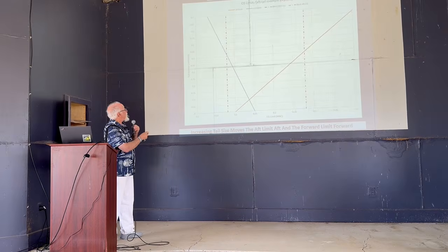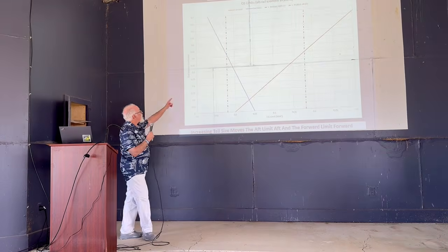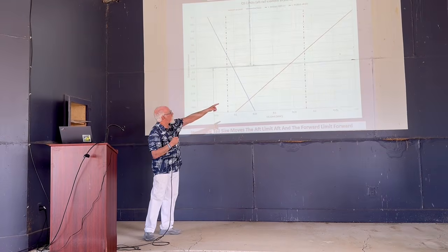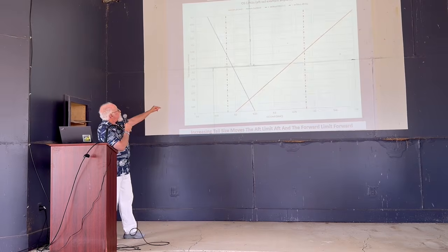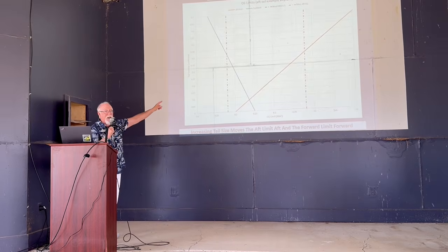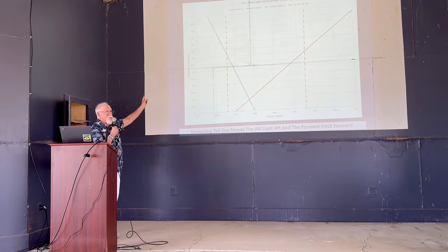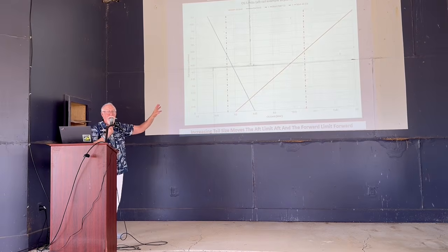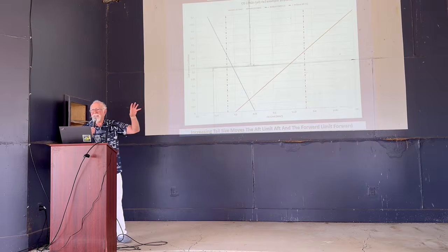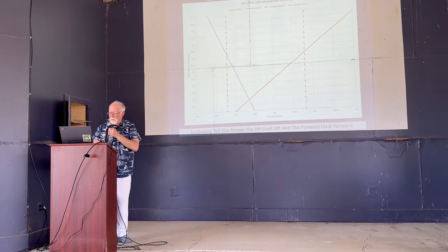And basically what you want is you can pick a tail size or a tail volume where, in this case, those dotted lines would represent the most forward and most aft physical CGs. And so on this particular one, this is a nicely balanced design. They both end up at about 40%, 0.4 tail volume coefficient is right. And you can tell from this plot also whether you're a nose heavy or tail heavy airplane by which of those two limits sizes the airplane. Ideally, in the perfect world, they both hit at the same time. The world is rather rarely perfect, but still.